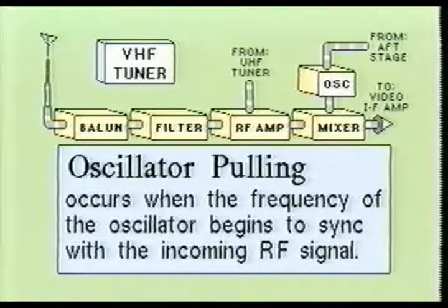As you recall, in order to produce an IF signal, there must be a difference signal being produced between the two heterodyne signals. Therefore, to avoid the problem of oscillator pulling, the oscillator and mixer stages are almost always contained in separate compartments within the tuner assembly.